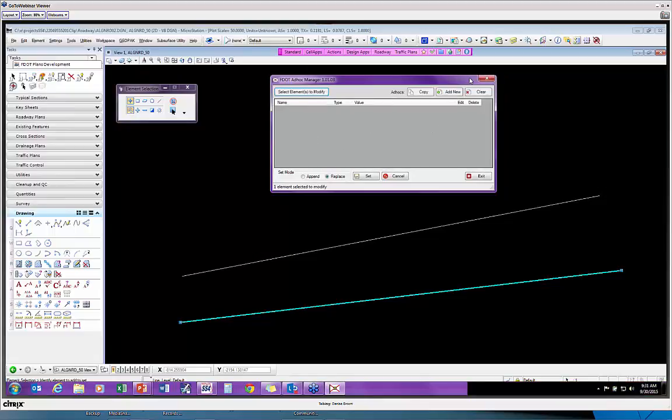By the way, as far as ad hoc goes, you don't have to use a DNC Manager in order to get ad hocs applied to your elements. There's a lot of our features that are set up so that they use what they call the native style. And the native style basically means it's going back to our DNC Manager in order to set the symbology. And part of what it is setting as well is the ad hocs.